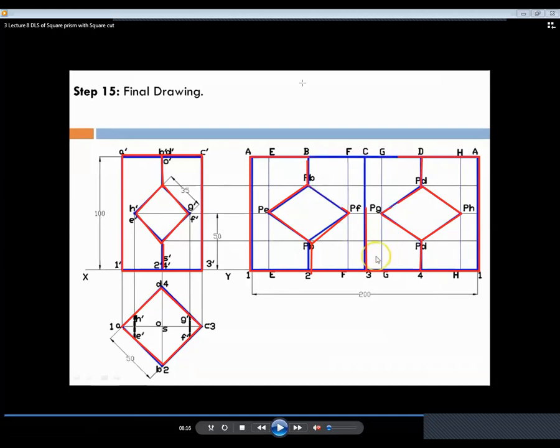Now see the faint lines. The projection lines are faint. I have joined them with yellow colored lines. These are the faint lines. The dimension line is also a faint line. The 200 dimension you have given is a faint line. Then the XY line is also a faint line, which you have to draw at the very first. The extension line for giving the dimension is also faint. The dotted line is also faint. You should not make it dark.